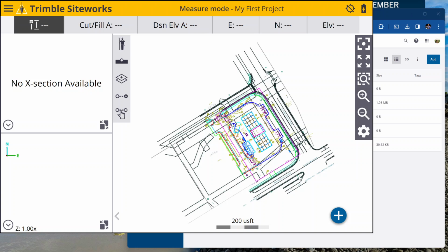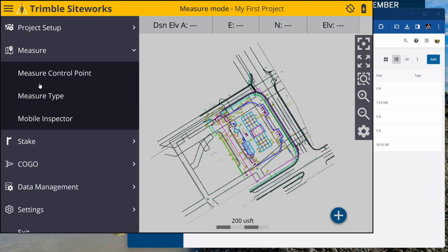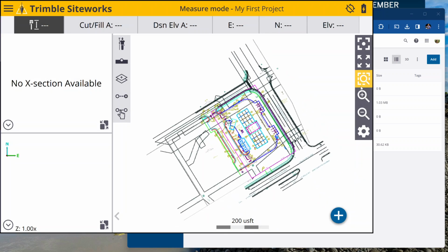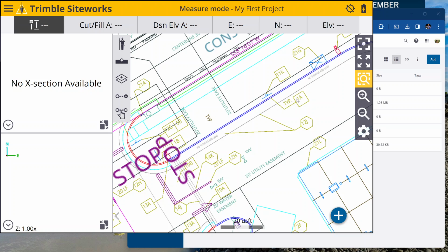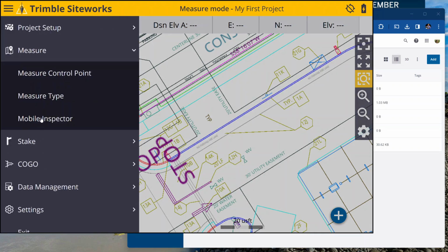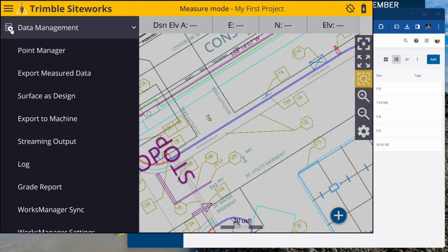Now you'll notice that we got a bunch of other line works because we didn't delete this line work from that site file, but we kept it in there in case maybe you need it. If you take a look, we can zoom in. If I zoom in on this, you can see we've got some call outs. So if we actually had the elevations, we'd be able to see what the elevations of the curbs were. So we could actually use that to stake out those, set those points, or mark the lath or whatever it is you're staking, paint it on the ground. You'd be able to use the other CAD data. Now we don't need this CAD data, so we're going to go into our data management, or I'm sorry, not our data management.